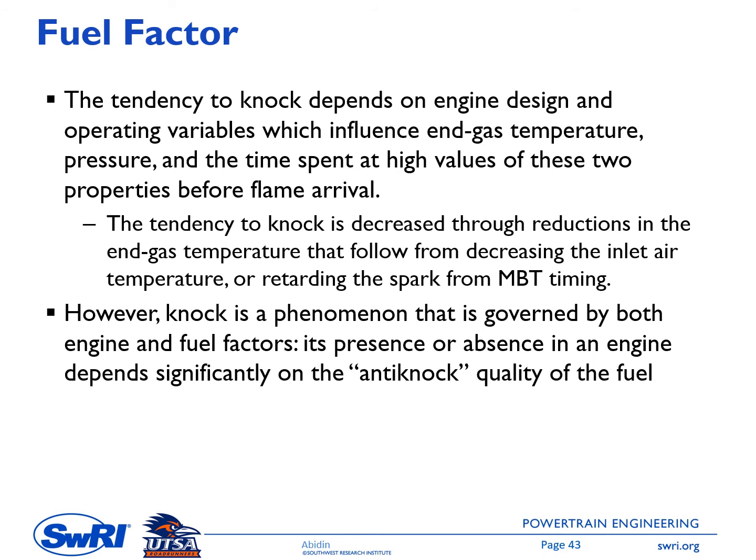Next one is fuel factor. The tendency to knock depends on engine design and operating variables which influence gas temperature, pressure, and the time spent at high values of these two properties before flame arrival. So the tendency to knock is decreased through reduction in the end gas temperature. So this knock tendency is strongly dependent on the temperature. And one of the parameters that represent this knock tendency is called ignition delay. So this is the time required for the mixture to increase the temperature from that corresponding temperature to ignition temperature.